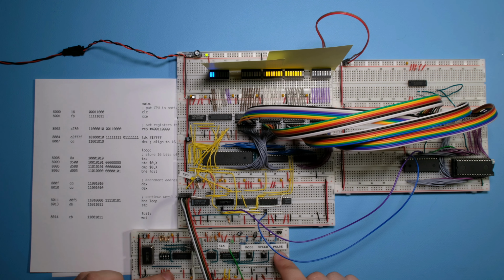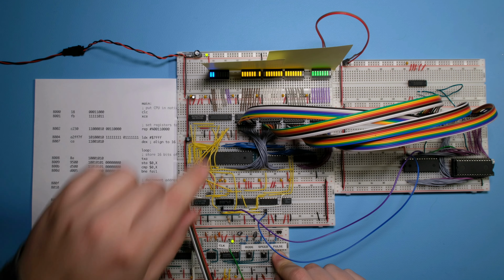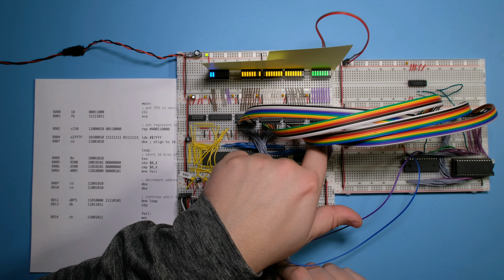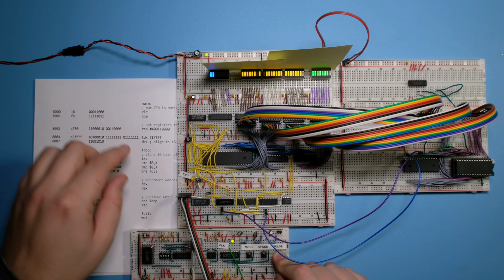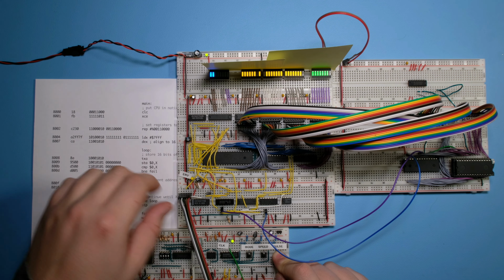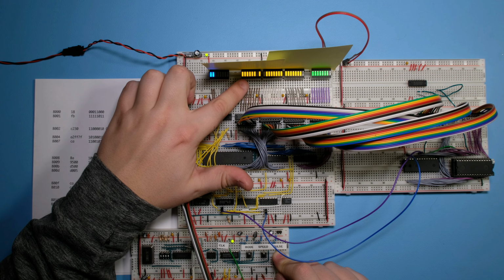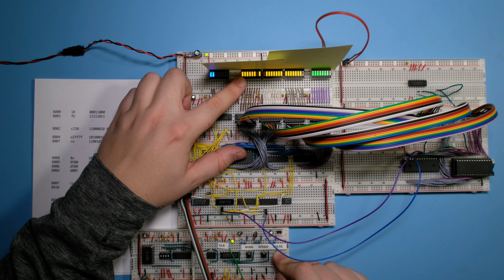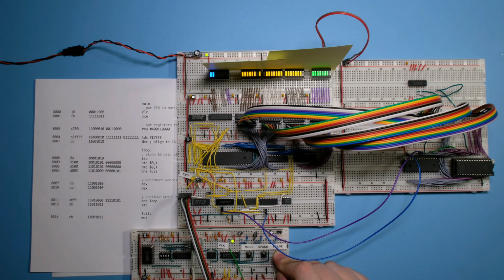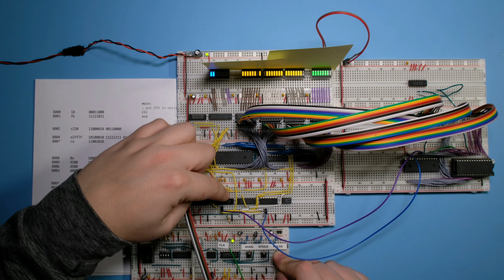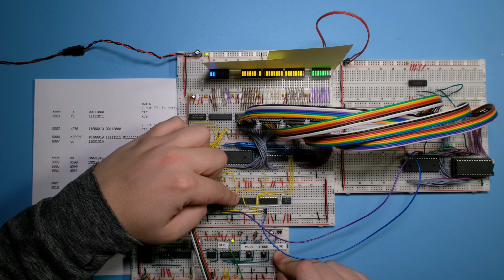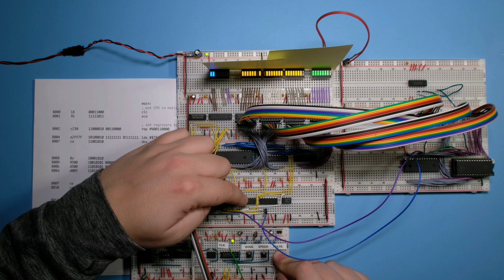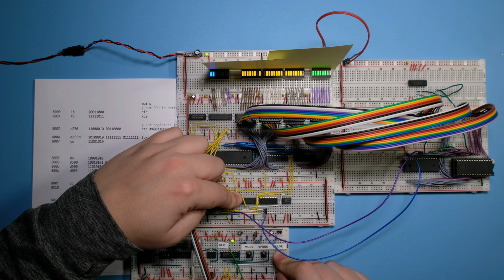So let me press the button here. And you'll see that the data bus lit up with the data that we want to write. That's FFF decremented one time. But you'll also see that the bank address lit up. And so that's curious. I think what's happening here is because I'm using just some random families of chip on this breadboard, there are HC families, so they're really slow.